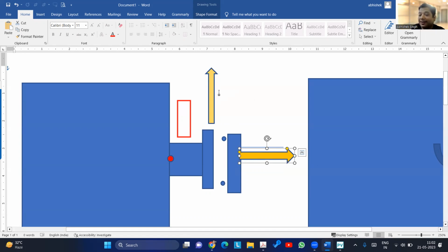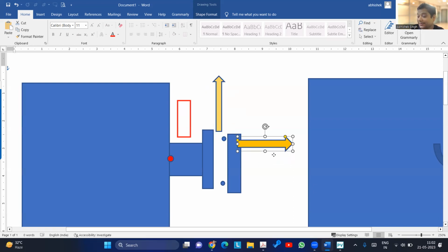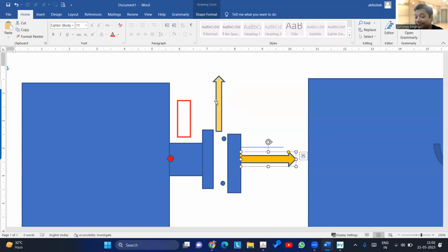While FL is in the perpendicular direction. So basically that bolt will experience some additional load. Other than that, your flange will not be affected by that. So what is impacting is P. FL and the circumferential direction load FC will not have any effect, and will not participate in the reduction of this.